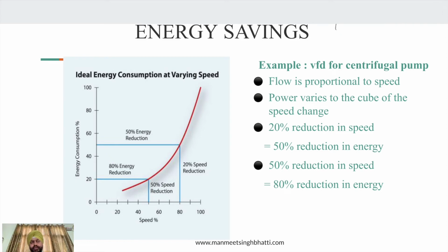It is some kind of short circuiting which happens, but normally it happens with a longer distance cable, like when the cable distance from the VFD is 500 or 600 meters. So sometimes those kinds of challenges come up. For that, you can put sinusoidal filters, you can put reactance, and all those things are available. We can provide you a study of the complete thing, how long a cable can go with the standard VFD, and based on that, you can decide on putting a line filter in between or not.